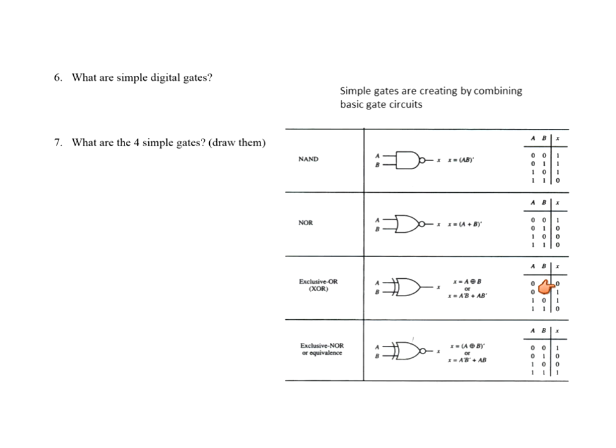All right, now, the exclusive NOR is exactly the same as this, but it's NOTed, which means it's the opposite. So the only time you get an output from an exclusive NOR is when you have 2 of the same on the inputs. Then you get an output. Anything that would be different on the input, a 0 and a 1, you're going to get nothing out. They have to be the same. So the exclusive NOR, they have to be the same inputs to get an output. The exclusive OR, you have to have 2 different inputs to get an output.